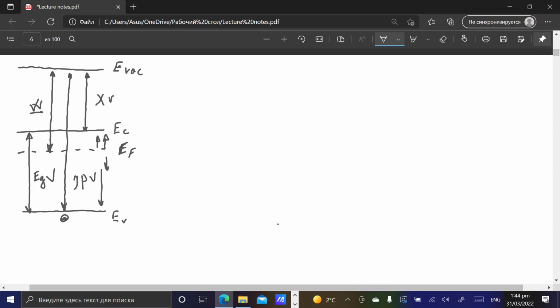So that means this parameter, the position of Fermi energy, is not a feature of the material, because regardless of this small amount of doping which we add, some less than a percent of atoms, we still have the same material. We don't change the material, but we change quite drastically the position of the Fermi level. That automatically means the work function will also change, because it counts from the position of the Fermi level to the vacuum level. So the work function is not a feature of the semiconductor material.